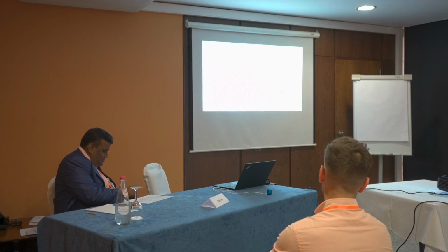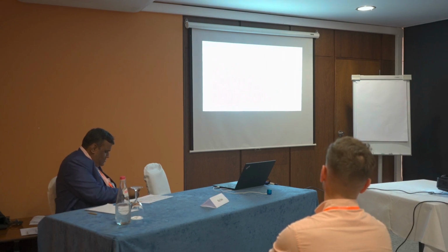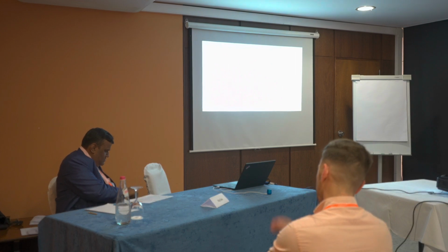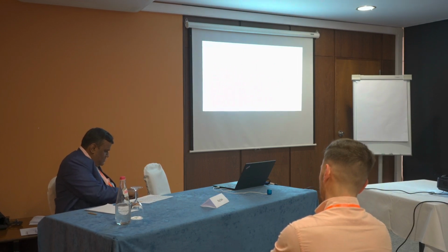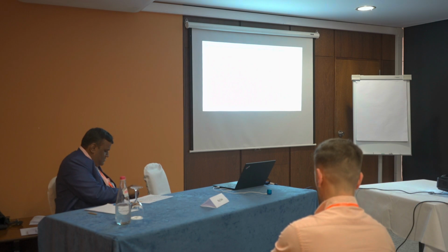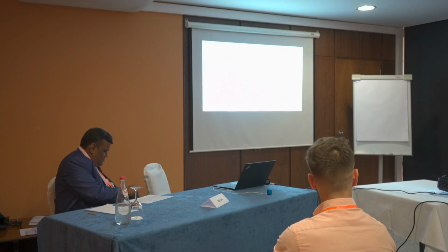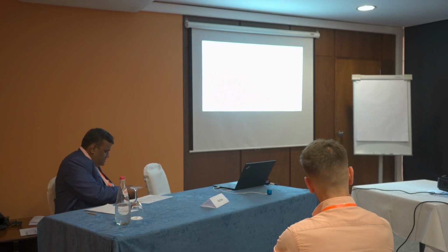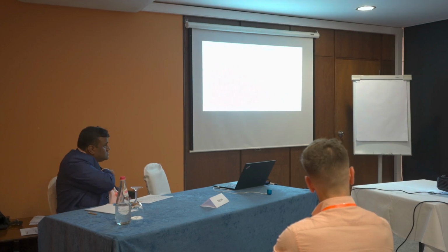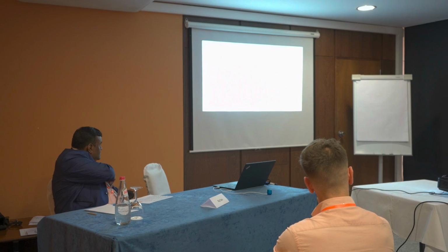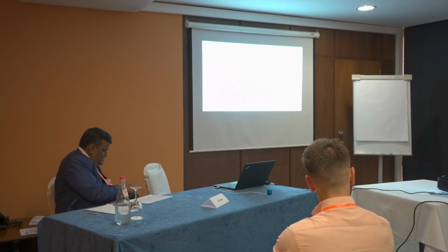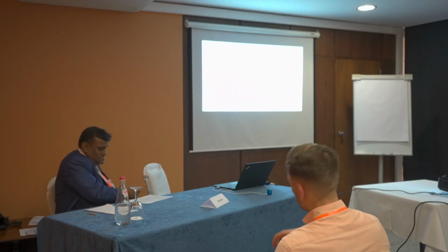The tests themselves are performed using Annex 14 of ASTM E1820 for larger specimens, and for the pre-cracked Charpy (PCC) specimen there is a special Annex A7. There exist a lot of results for the small pre-cracked Charpy specimens, but not for larger specimens like 1-inch CT.